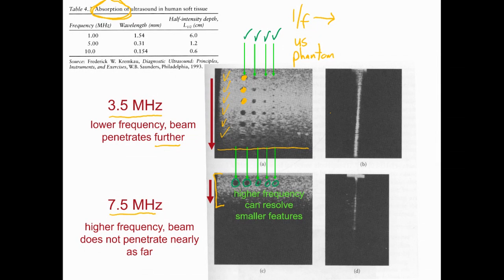And as I said, that's the trade-off with ultrasound. When you go to higher frequencies, you can resolve smaller objects, but the beam does not penetrate nearly as far because the absorption goes as 1/f.